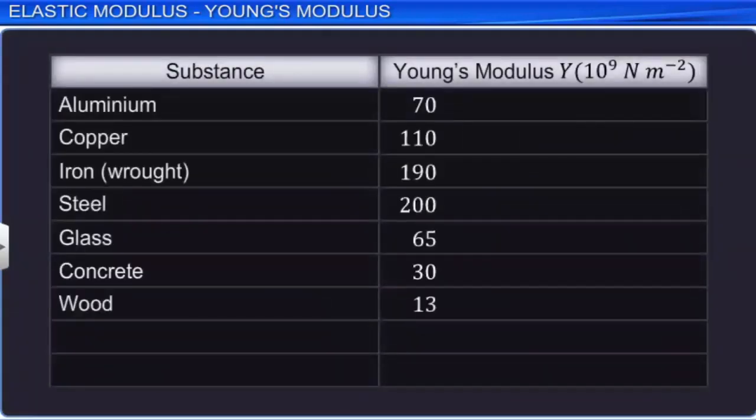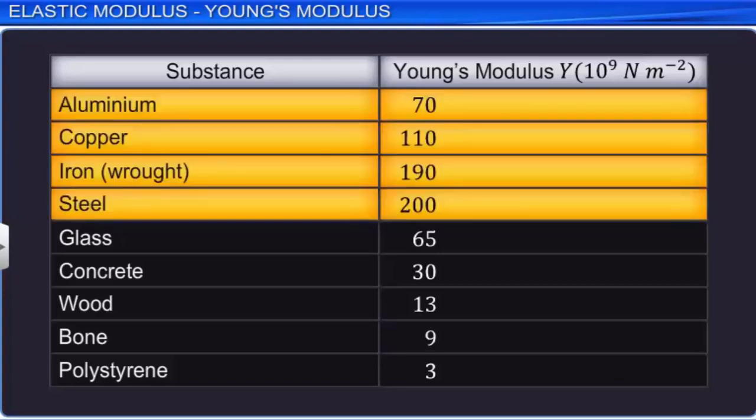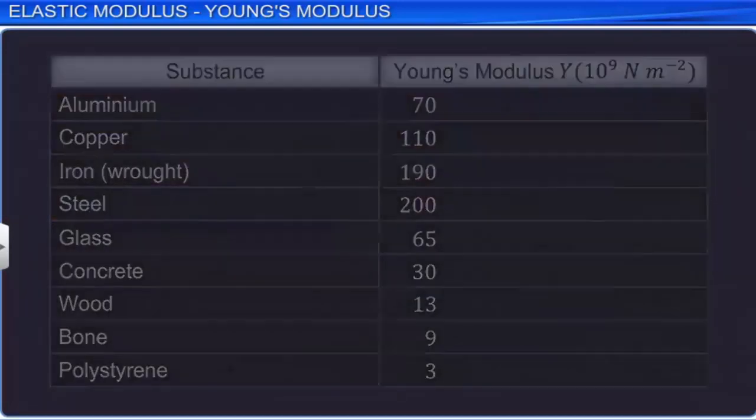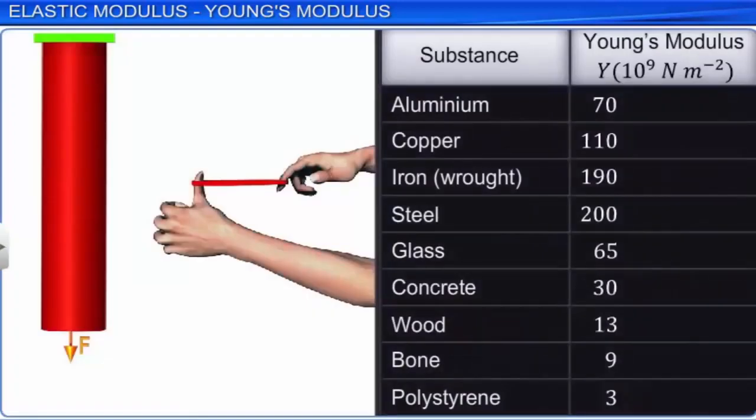It is a common misconception that rubber is more elastic than a metal, such as steel. This is because you see a rubber band stretching to more than double its length very easily. But steel does not display similar extension. In scientific terms, the higher the Young's modulus of the material, the more elastic it is. This is because a higher Young's modulus means a larger force is required to produce the same amount of deformation in bodies of the same dimensions.